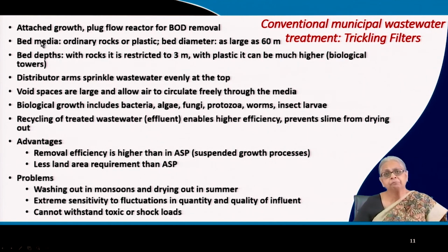When I said attached growth, it means you have to provide a media on which the bacteria will grow. So this media can be ordinary rocks, stones, or plastic. And these are some of the most common materials that are used. The size of these reactors can be huge in both cases, ASP as well as trickling filters.